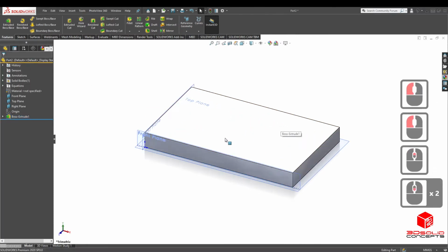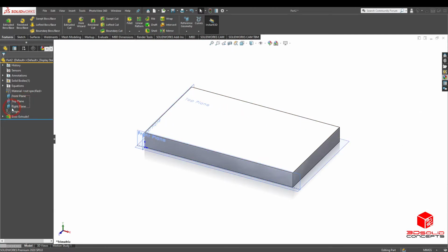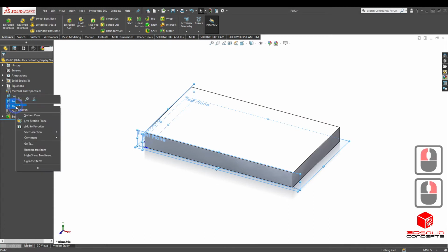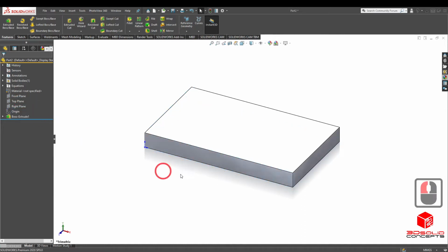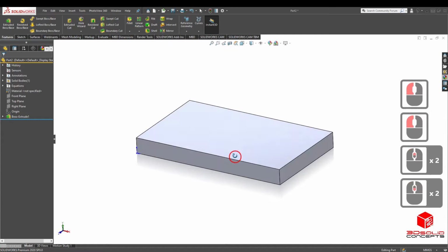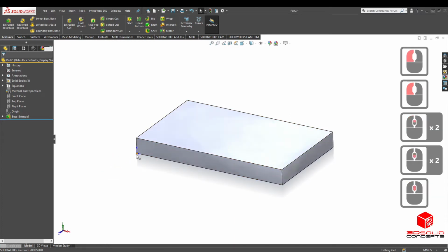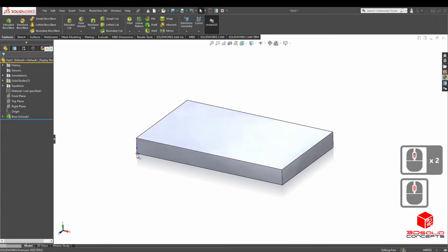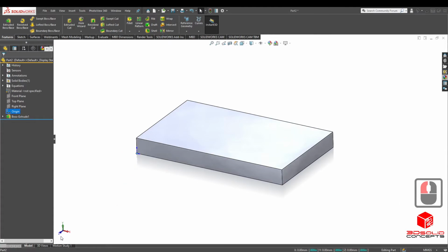So, as we are now, we can orient ourselves so we no longer need these planes. They're a little bit distracting. So what I like to do is make sure you click all three of these, you right click, and you click this eyeball symbol with the slash across it. That basically tells it to hide. And we can see our origin is right here in this blue marker, and it's the correct orientation still, Z, Y, and X.